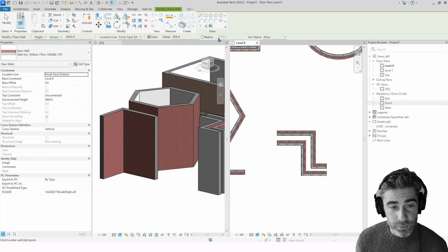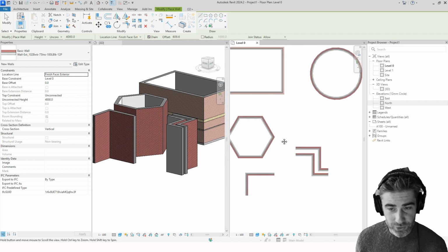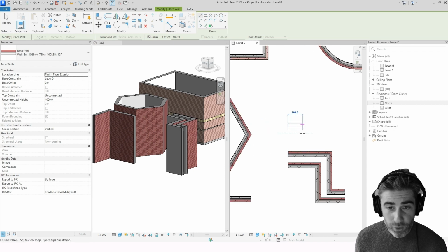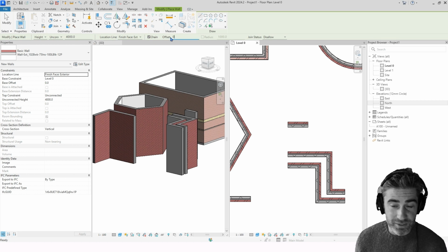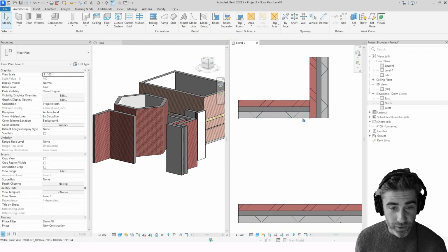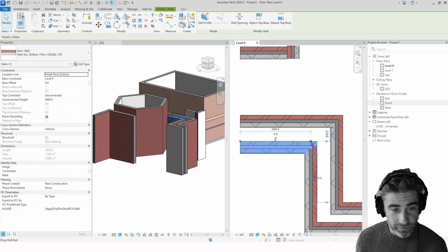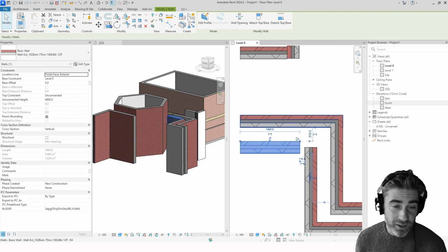The radius, this is where it adds a curve of a specific radius to connected walls as you're drawing it within your model. We then have the join status. This is where it allows us to allow or disallow automatic wall joins. Walls in Revit will automatically want to join. However, there are some instances in your project that this is just not the case. You don't want this join. So you can select this as you're drawing the wall. Or if you've realized afterwards, you can select the wall itself, right click on the wall grips, and hit on disallow join option in the options menu.